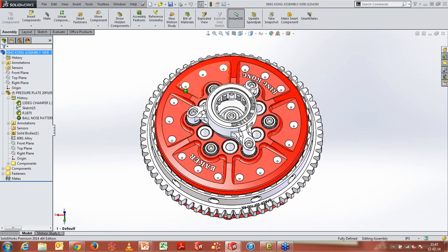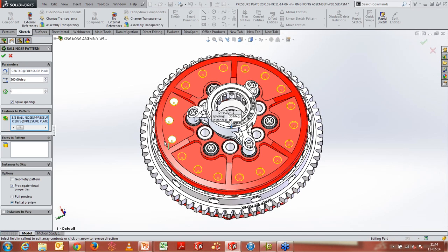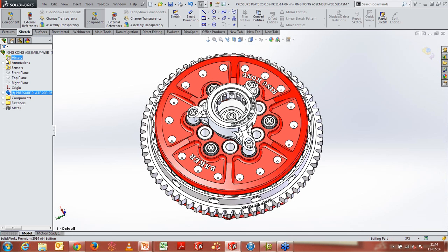So let's say, for example, you have a particular part, and especially for this particular part, I have this particular feature that I keep on changing. So this is a circular pattern feature. I keep on changing it every time, right? So since I keep on changing it every time, let's say you make changes to it more than 3 or 4 times, SolidWorks automatically understands, okay, this is the one feature or this one particular sketch that you keep on changing every time. So it will put it directly inside the history folder.